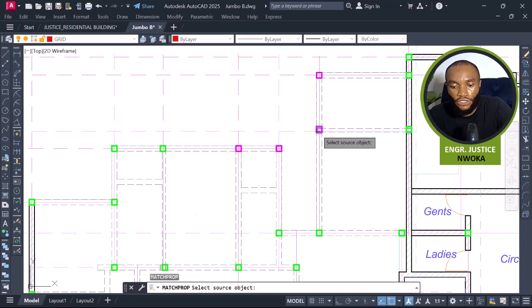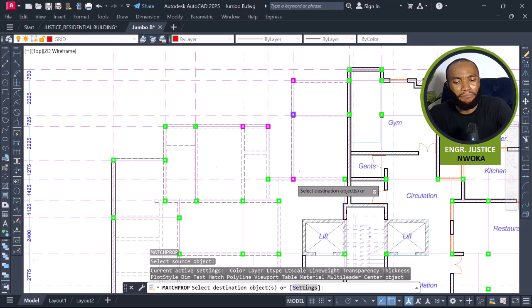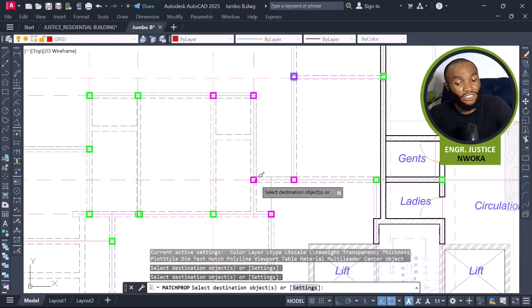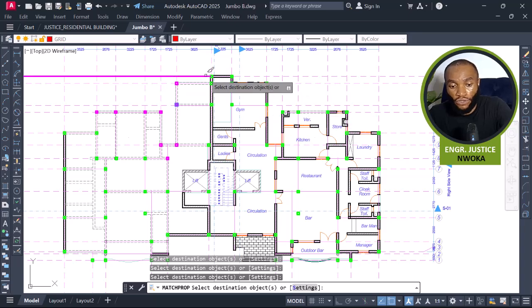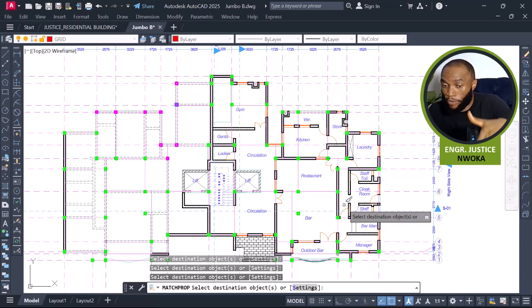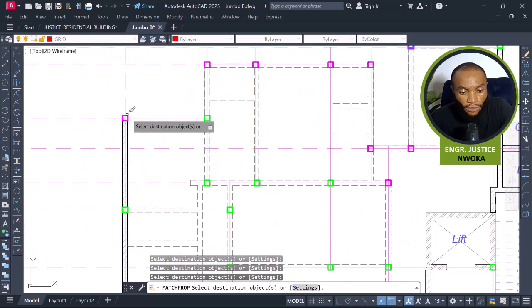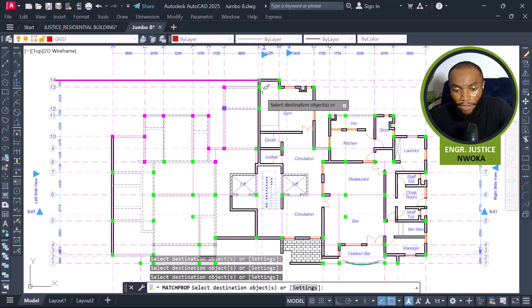That's because when they come to the basement here, they are going to be buried inside the soil, 3.8 meters down, which is a waste of material. So we're going to stop these columns on the ground floor. While the ones on this green side, we want to support the basement. That's fine. All these ones now will stop. This is just normal block work, so we are not going to design this one here. We are only focused on the basement side here.